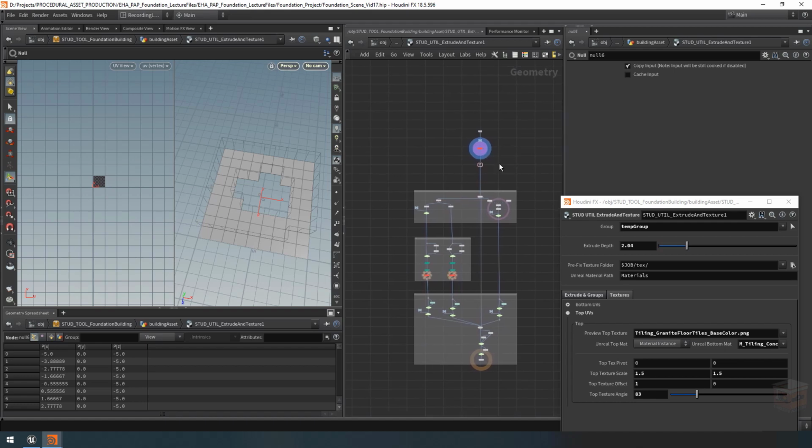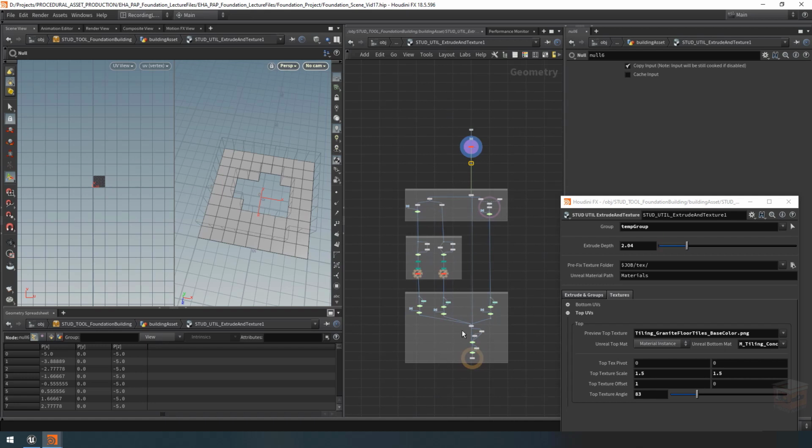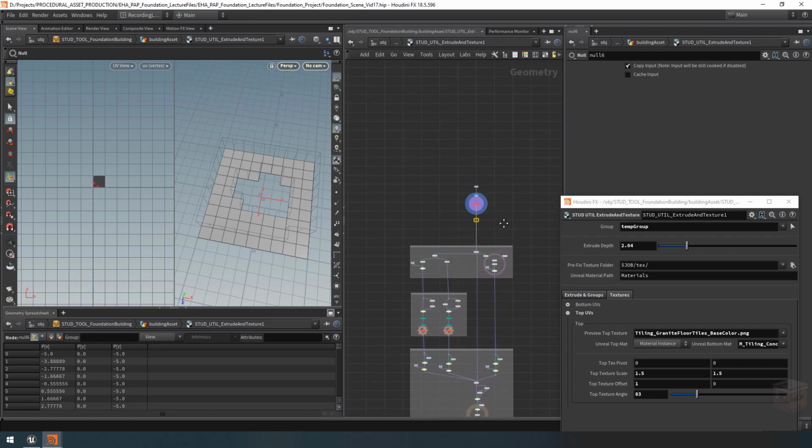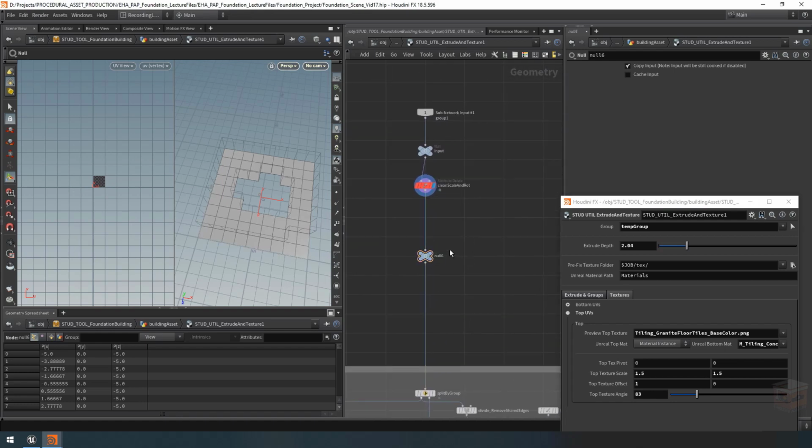Now, I'm not going to go into compiling too much right now, but basically if I calculate all my variables out here and I make sure it's in line, then this will always calculate before everything else. So once I do the optimization pass on my toolset and this node will be compiled, right, it will always calculate this bounding data first, and then all the other nodes will grab from that. So we don't get some kind of order issue with the compile node. I won't go into that too much right now, but it's an issue I want to deal with right now.